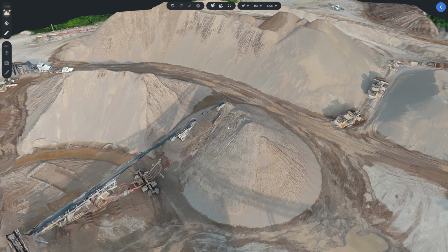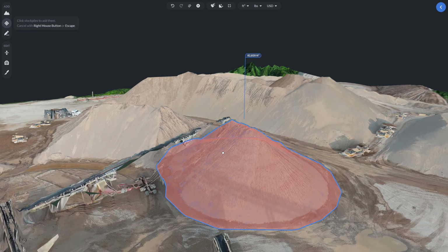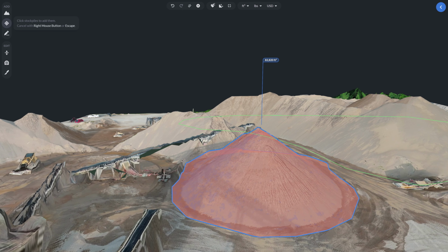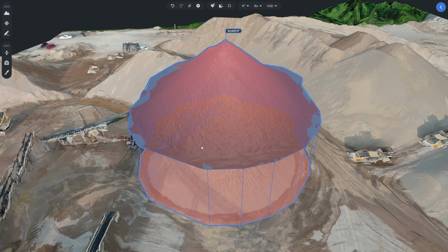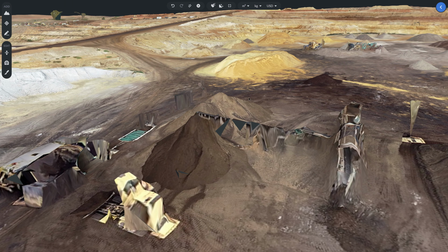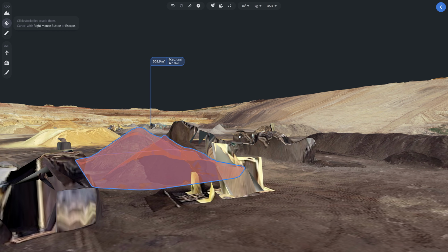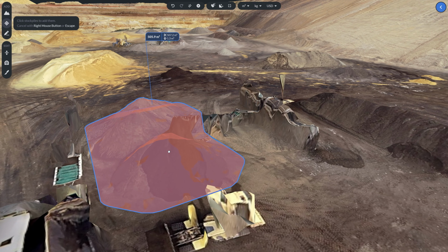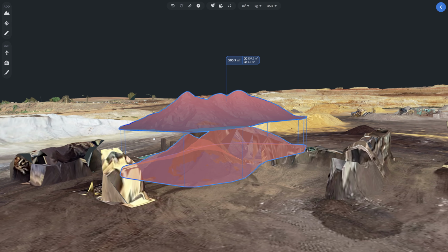StockpileStudio calculates volumes from the project's digital elevation model, analyzing surface geometry, slope, and elevation continuity to distinguish material piles from surrounding terrain. In most cases, non-material features such as conveyors, stacker booms, light vegetation, small equipment, and minor terrain irregularities are not incorporated into final volume calculations. This is achieved through confidence-based detection that prioritizes stockpile-like morphology and filters out inconsistent surface features.